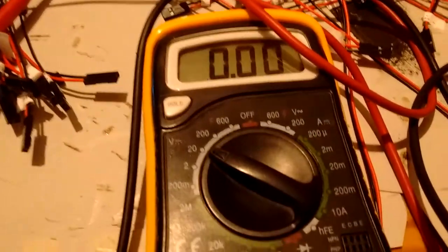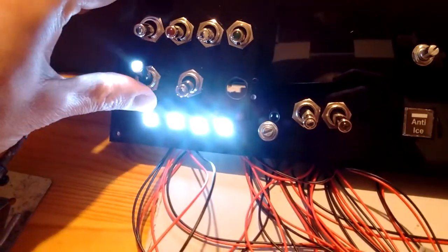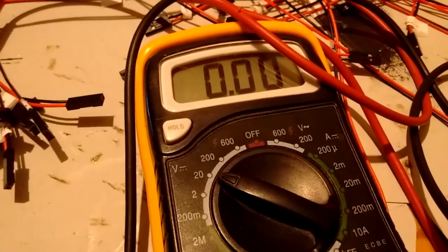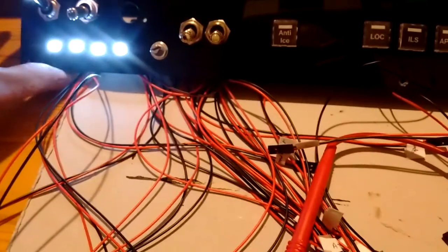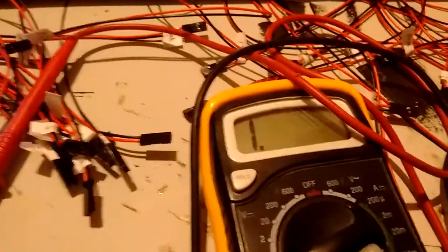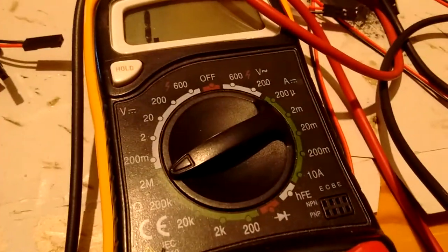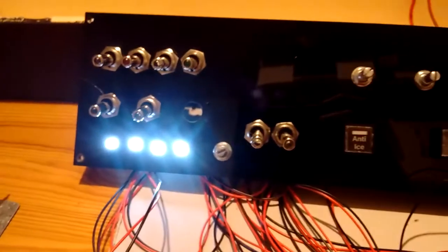I did a little mounting with two DuPont pins and cables to test the buttons one by one. We must verify that the button is contacting correctly and there is no voltage on the DuPont cable. So we have the multimeter in volt position, we see there is no voltage, and I put it on ohm position to see if it contacts correctly.